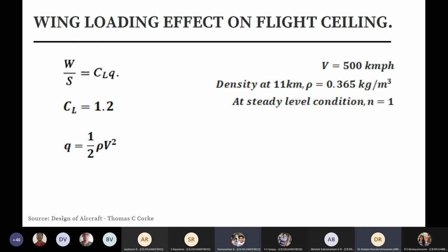When you fly, the wing loading keeps changing, so you are just getting an idea. Now, if suppose we are assuming some CL around 2, why are you assuming that CL to find the wing loading? So this wing loading is something for you to work with and get the initial idea.